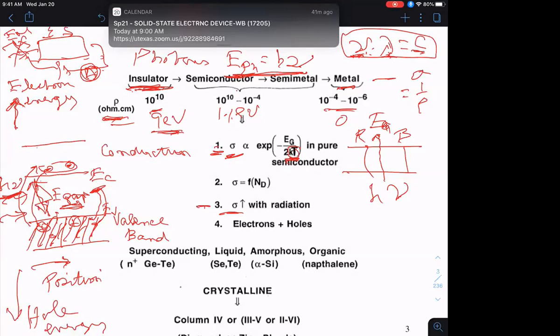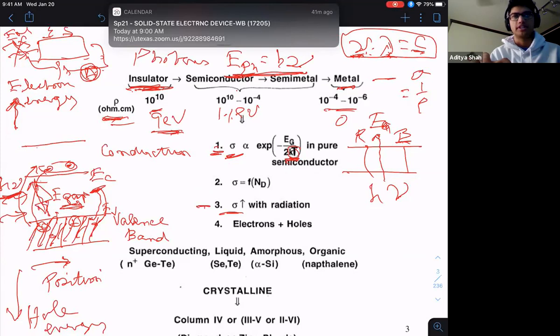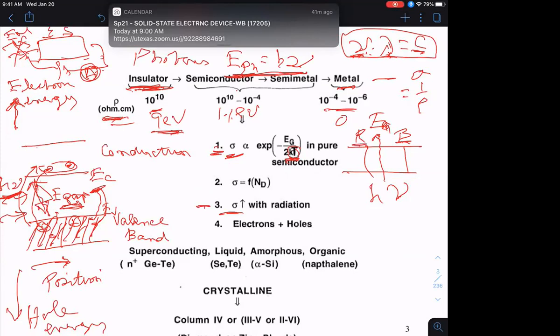That semiconductor, would that absorb or transmit the blue photons? It would absorb them because they have an energy greater than that of the band gap. Excellent. On the other hand, the red photons would not be absorbed. So if I take a semiconductor like that and I hold it up against white light, that semiconductor will look red because the red colors will be transmitted through, okay?